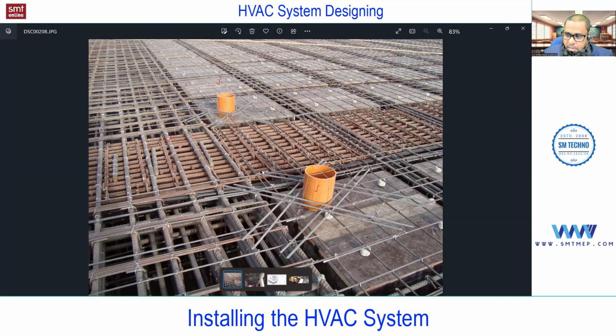I can see that all the sprinkler lines pass through the beams only. And even the chilled water pipe can pass through the beam. But initially, the pipe sleeves are required at the time of construction only, and the construction should be as per the design. Okay, I'll show you this at the time of piping. I'll show you some images. In that, you'll find the pipe sleeves for chilled water, for firefighting, even for plumbing. That is accepted, no issue.